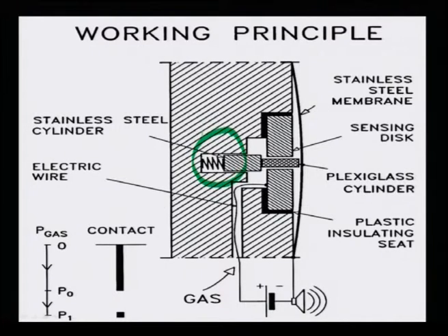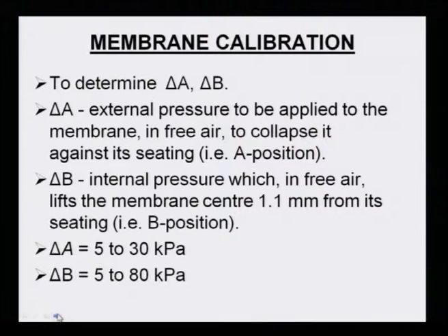By means of gas, once it enters, it will try to expand outside. The moment it expands outside, the soil will give resistance. So this resistance, or the sigma 3, you can get from how much this spring will be compressed. There are two parameters required to find it out.